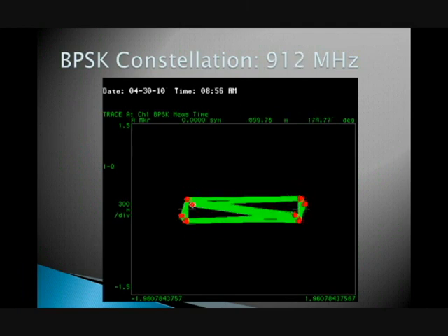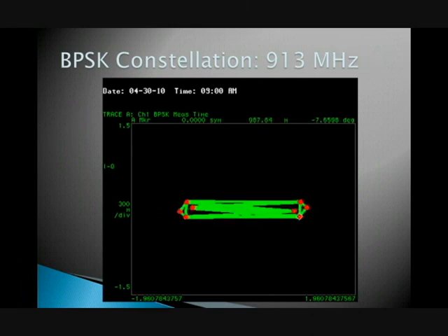These are the BPSK constellation diagrams. As you can see, the signal fidelity is still intact. Ideally, these constellation diagrams would only have a left to right orientation. This vertical component can be attributed to noise in the channel.